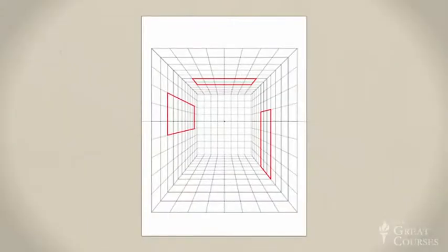First, we'll draw its footprint, 2 feet by 2 feet. Locate this 2 feet from the left wall and 1 foot in from the picture plane. Next, on the left wall, at a depth of 1 foot from the picture plane, note the box's 4 foot height with a vertical line. Now, carry the height measurement over the footprint with a horizontal construction line. This locates the box's front face, and you can draw it in. Then, erase all the construction lines except for the footprint.